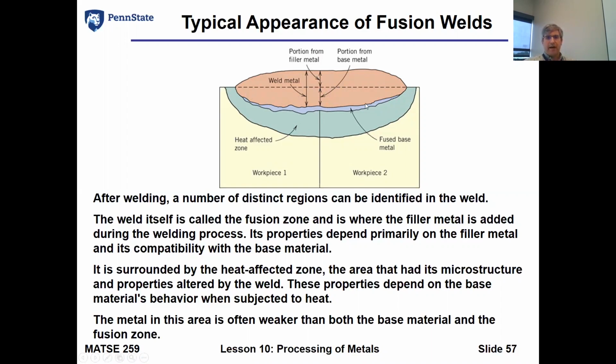The second one is what is fused base metal. So we've gone below, and we've actually melted some of the base metal together, and so we can call it a fused base metal. I like to call this a dilution zone. And then next to that, we still have pretty high temperatures because we're melting metal up here. And so with that, we create solid state phase transformations because of the high temperatures that each of the two work pieces have seen. This is called a heat affected zone. No melting generally in a heat affected zone. So that's important. This is a solid state process.